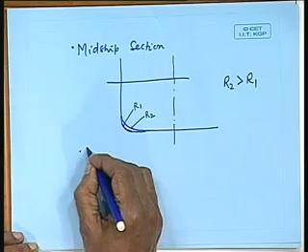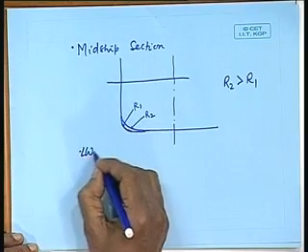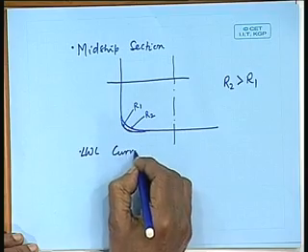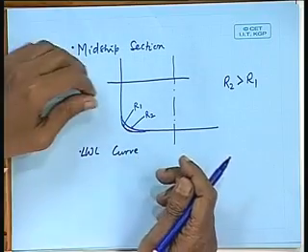Okay. Then the next important item in this is the water plane area, water plane curve, load water plane, LWL curve. We have seen the sectional area curve. We have already discussed the role of half angle of entrance in the class when we discussed wave making resistance. Do you remember?